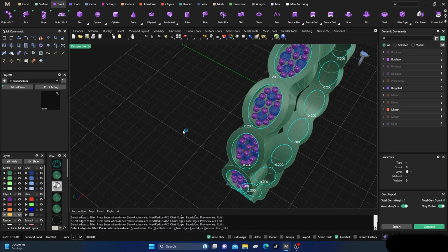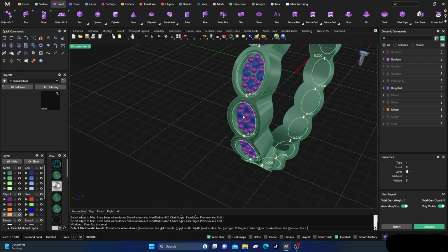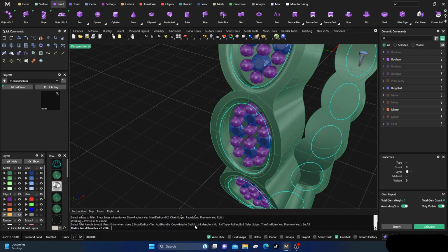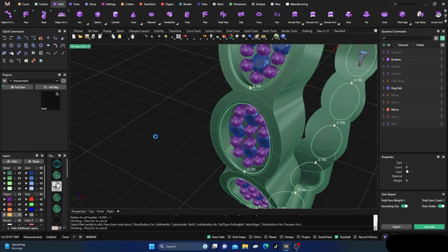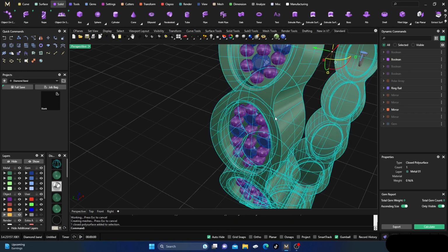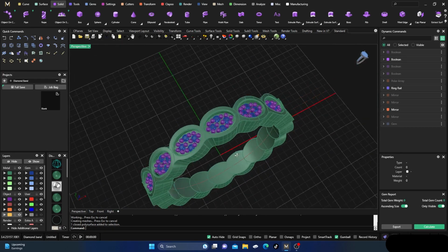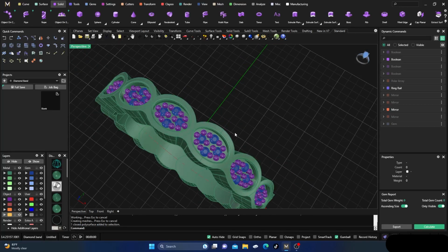Select each individual edge, and we're at a 0.2. We know that's going to work, but it's not going to work, right? It's going to give us naked edges right in here somewhere. So let's go ahead and go to set all, and we'll try a 0.1 and take a look at that. And yeah, that's probably much better. Okay, so let's go ahead and hit enter. And let's select our item, and now we have a closed poly surface, and we have little rounded edges going off around there so far. Okay, so far so good.